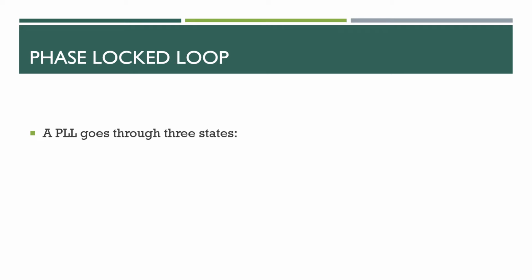So taking the part here, initially when a signal is not given to the phase detector, that is, there are no input signals applied to the phase detector, the phase detector output will be equal to 0. If the phase detector output is equal to 0, the oscillator oscillates around its own frequency. We call it a free running frequency there. So that is a free running state, what we can say, free running state.